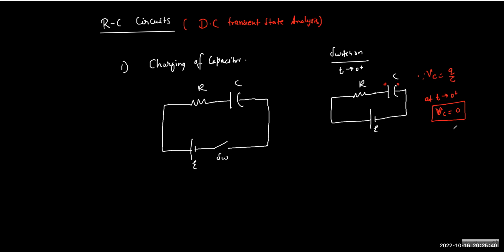And if there is no potential difference across a capacitor, then what is the role of the capacitor here? It will act as a conductor, a conducting wire. It is now short circuiting the terminals across it. So you can replace it just like a wire, and then think of the remaining circuit.